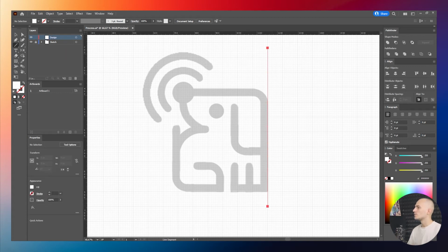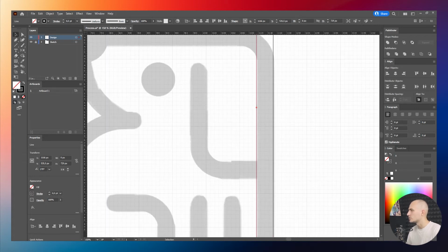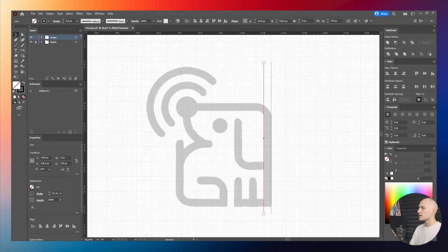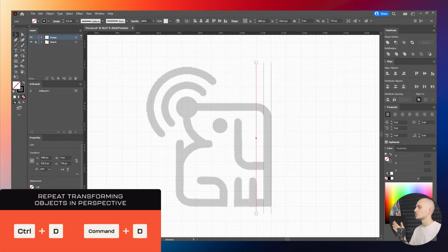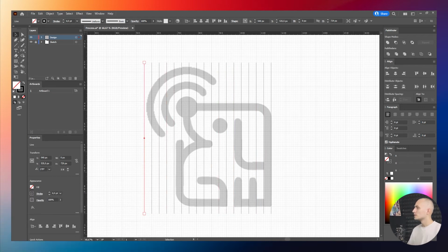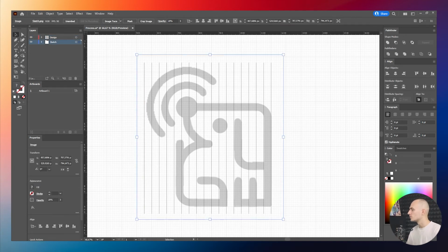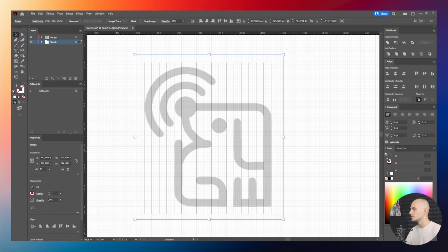Now let's draw a vertical line, and after selecting, copy it to the left with the Alt-Shift key combination. And now, with the given step, create more additional lines by duplicating them using Ctrl D. Here we go. Since at the very beginning we set the snap to grid, all these lines fit perfectly into the grid. Of course, now we should create horizontal lines.